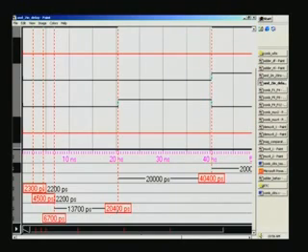That's what it means. Another thing that you see here is you can set as many cursors as you want. For example, you want to measure the time interval between one point of time and the next transition, how much time it has taken. What you can do is just make a cursor, which we'll be seeing in ModelSim, although the visibility will be poor, I'll explain it. You can click the cursor here and then say add the cursor. Then this dotted cursor will be put on that point of time.